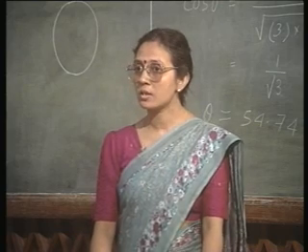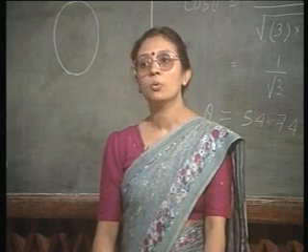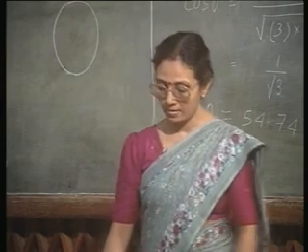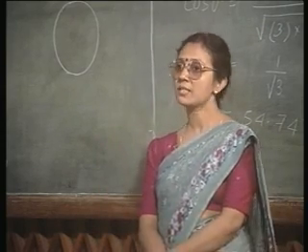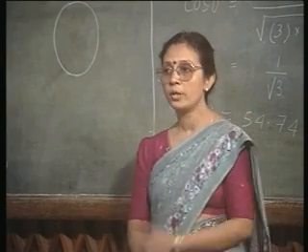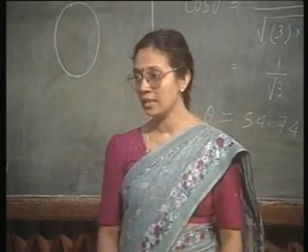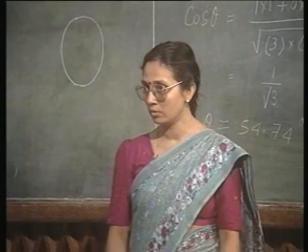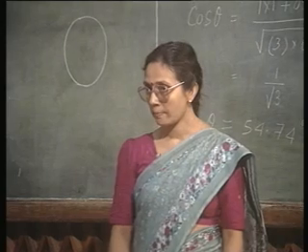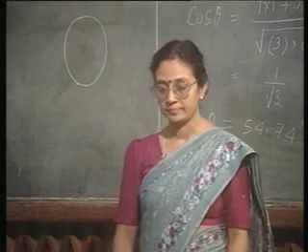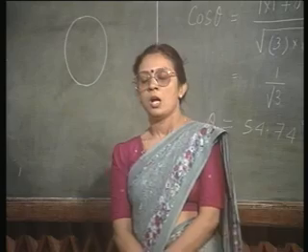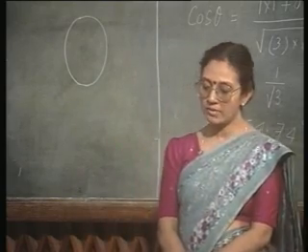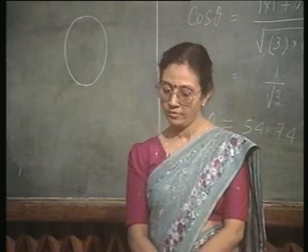And what is that natural cleavage plane? Obviously 1 1 1, because 1 1 1 has the highest modulus of elasticity and the highest tensile strength. Therefore, when you cleave a silicon, the plane you expose is going to be 1 1 1. Agreed? So, 1 1 1 is the natural cleavage plane of silicon. Fine.